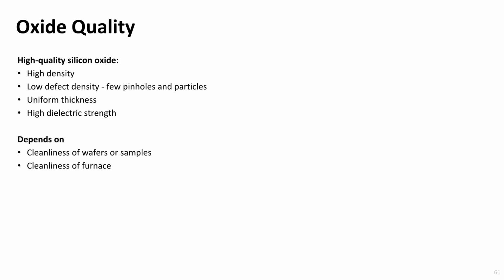Even a small amount of impurities will negatively affect the grown oxide quality. While some contaminants will grow with the oxidation and remain on the outside of the oxide layers, others are incorporated into the grown oxide film. For example, impurities, like sodium or potassium or metal ions, can diffuse through the oxide layer and heavily reduce the oxide quality. Depending on the application, this can render samples to be useless.